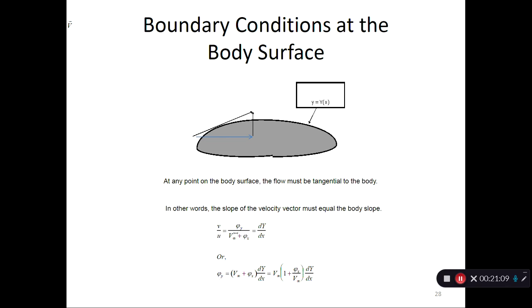Now I can bring this v infinity plus vx to the other side. Then I take a v infinity out of it. Then I get 1 plus a disturbance, which is a small number, times another small number. Why do I call this a small number? Because mild camber, small angle of attack, thin aerofoil. That means the slope is going to be like 10% thick, 12% thick aerofoil.